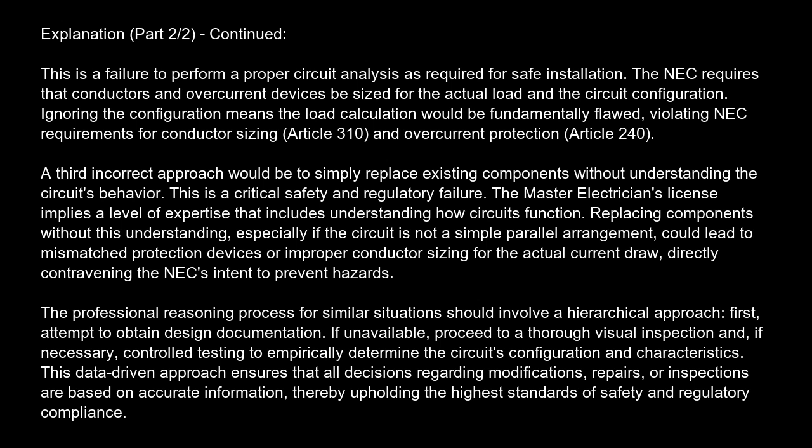This is a critical safety and regulatory failure. The master electrician's license implies a level of expertise that includes understanding how circuits function. Replacing components without this understanding, especially if the circuit is not a simple parallel arrangement, could lead to mismatched protection devices or improper conductor sizing for the actual current draw, directly contravening the NEC's intent to prevent hazards.